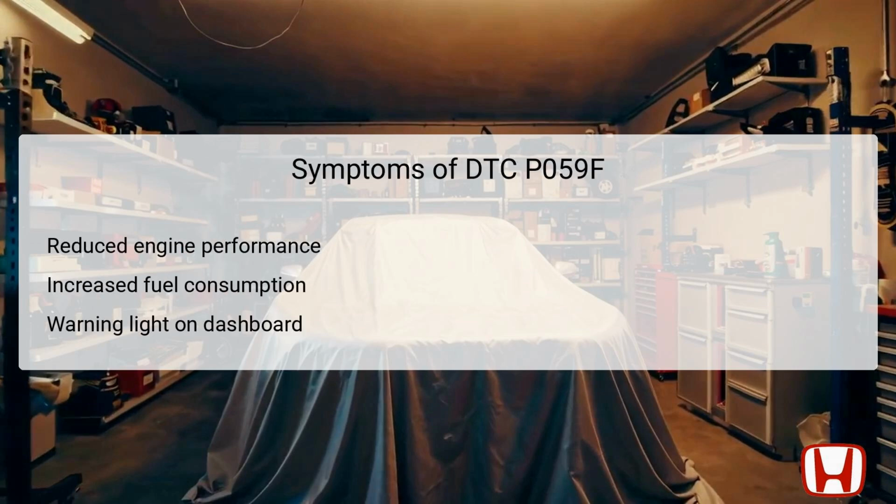When DTC P059F is triggered, several symptoms may manifest. Drivers might notice a reduction in engine performance, which can lead to less responsive acceleration and an overall sluggish feel. This malfunction can also lead to increased fuel consumption, as the engine works harder to compensate for airflow inconsistencies. As a direct result of the fault, a warning light will illuminate on the dashboard, alerting the driver to an issue within the vehicle system. Being aware of these symptoms can prompt timely inspections and repairs before further complications arise.